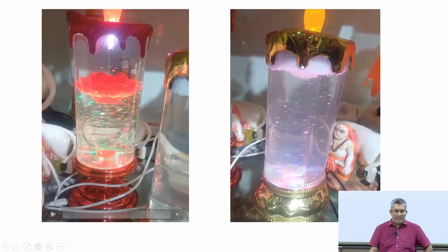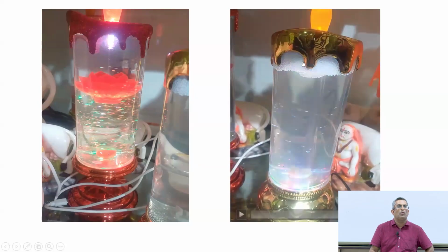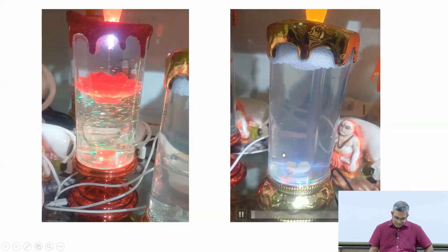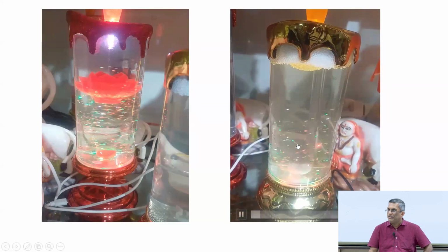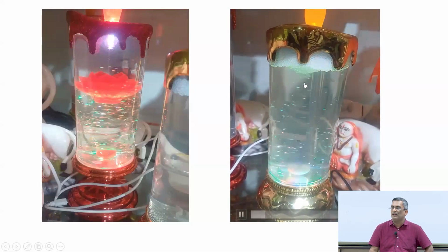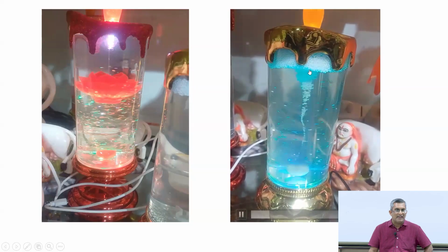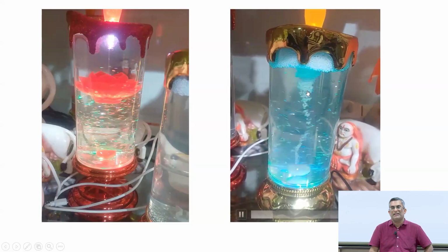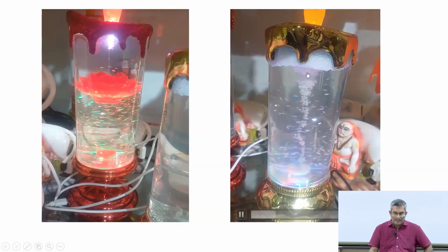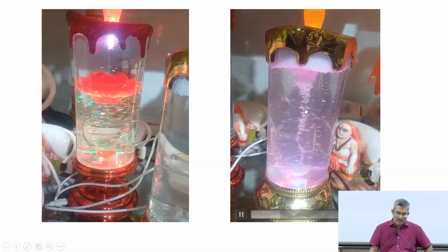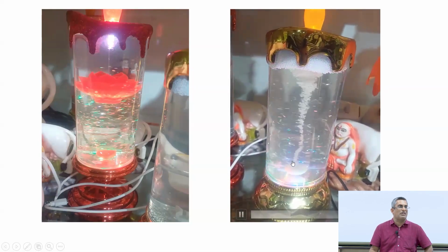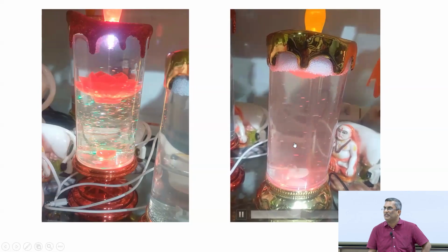Nothing. In the right one, we have some flow tracers. What is meant by flow tracers? The particles which somehow track the flow. And possibly what is happening is that as we have this rotational motion imparted on the liquid, it creates a low pressure zone at the center, and that causes the particles to be dragged down, and you see a clear presence of a vortex core. A very nice, beautiful vortex core is present.